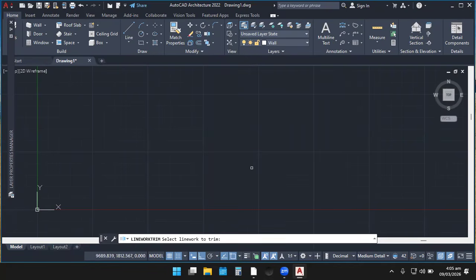Or if you want to use the mouse, you right click the mouse. After clicking escape, it was gone. So don't worry, we'll play with it next time again. So first of all, let's pick a line. When I pick my line, you realize that my auto is activated and my object snap is also activated. So I'm good to go. Always make sure these two things are activated.